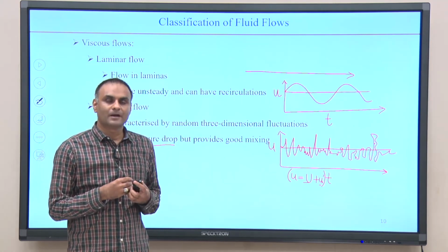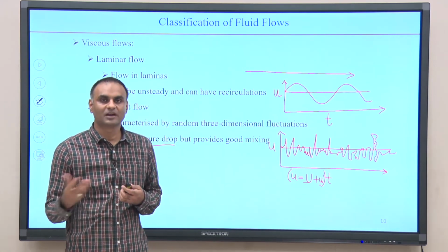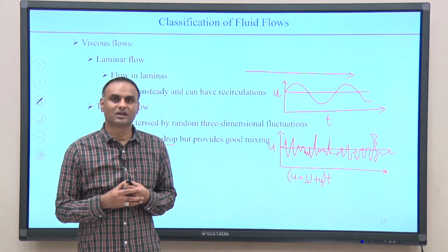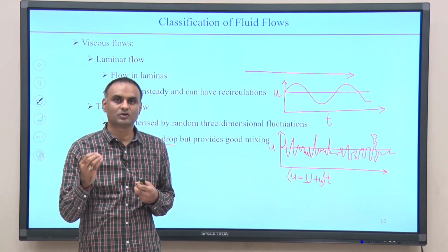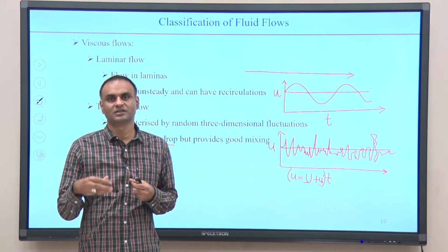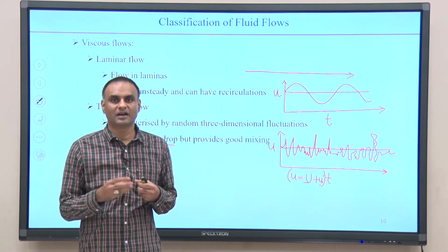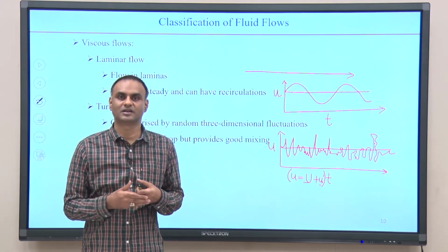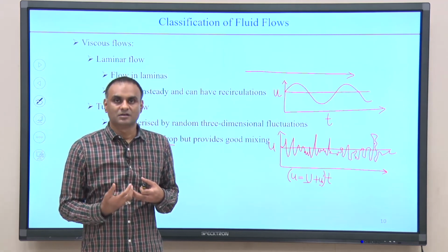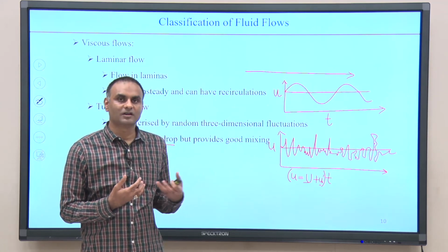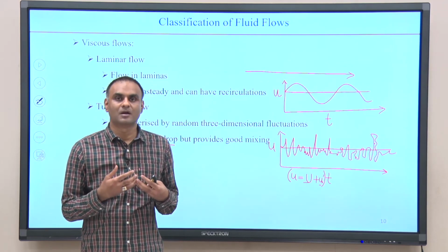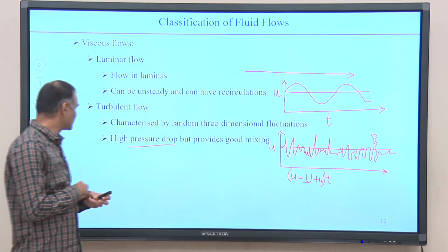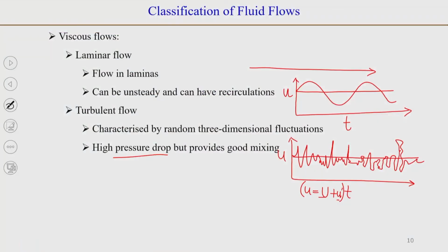In one of the recently emerging areas, which is called microfluidics or chemical microprocessing, there are a lot of advantages, but one of the problems is that the length scales are small. So, of course, the corresponding velocity scales will also be small, and consequently the Reynolds number is low. The flow is laminar. When the flow is laminar, there is no inherent mixing which we generally get in large reactors. Therefore, a lot of effort in microfluidics is directed towards developing mixing devices, passive or active. So, turbulent flow offers very good mixing, which is good news from a chemical engineering perspective.